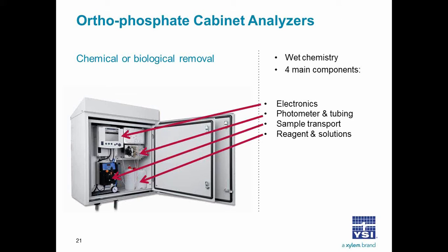Features of an online analyzer. Desirable features are low reagent consumption to save money, suitability for outdoors so the analyzer can be located anywhere in the process where it's needed, automatic calibration to ensure you are assured of the accuracy of the measurement, an integrated permeate pump, and a filter module that allows you to withdraw a sample directly from the mixed liquor.